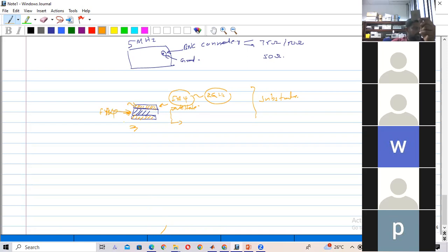And this is a copper coat, and this is another copper coat. So this is called the substrate material, and there are many substrate materials. This is FR4 material, and there are others, Neltec, Rogers, likewise, used for high speed application. But FR4 is not good for high frequency; sorry, not speed. Up to 2 gigahertz it is okay, but for higher frequency, 30 gigahertz, likewise, we need to use Neltec or Rogers.